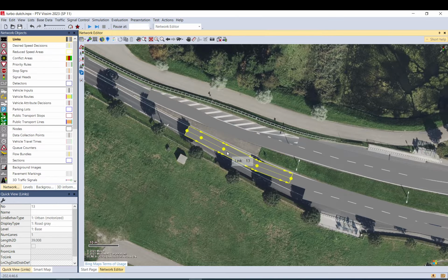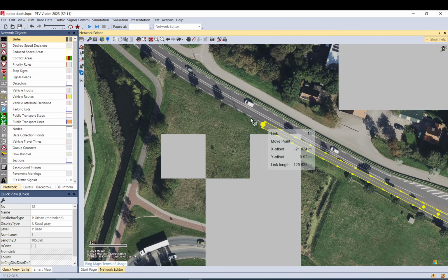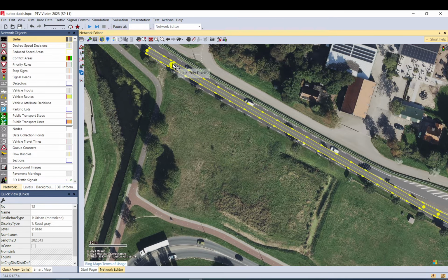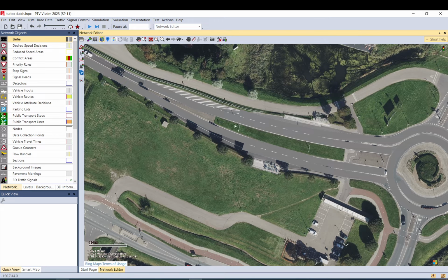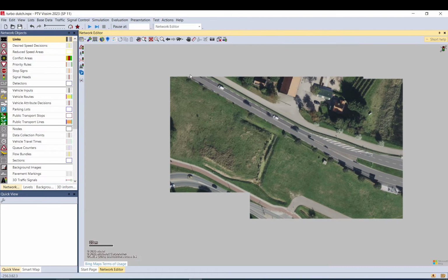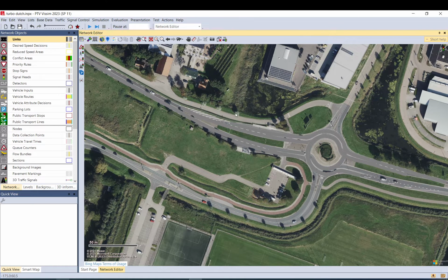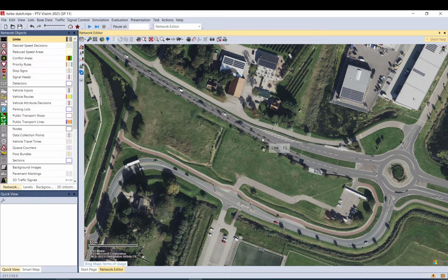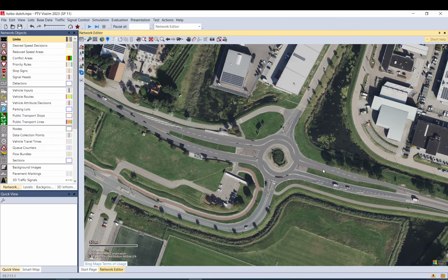They can exit there. For the entry links, you always want to extend the entry links reasonably long because you want to capture any queue occurring. For the exit link, it doesn't matter because vehicles exit without a constraint. Of course, if you have a constraint on the exit, you want to consider something there. I talked about this in the Jacksonville example, so have a look at that if you are interested in why and how to deal with it. I mentioned a few examples there.